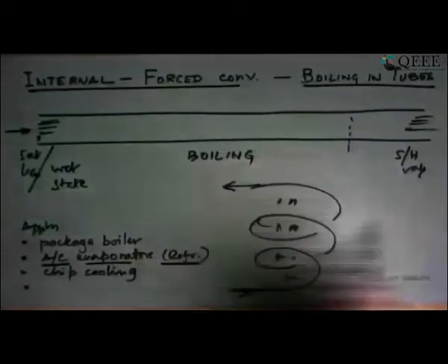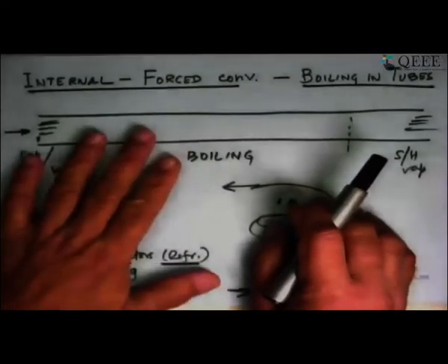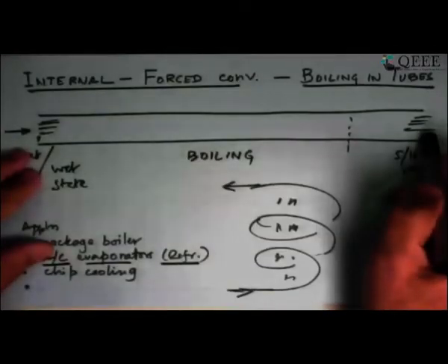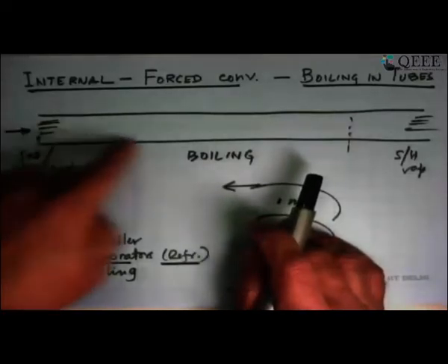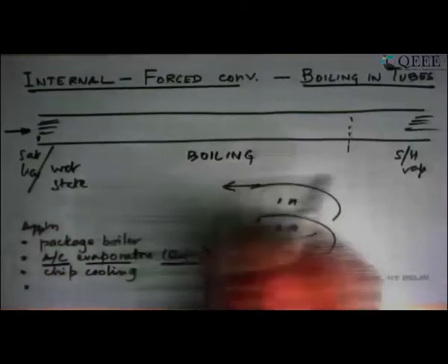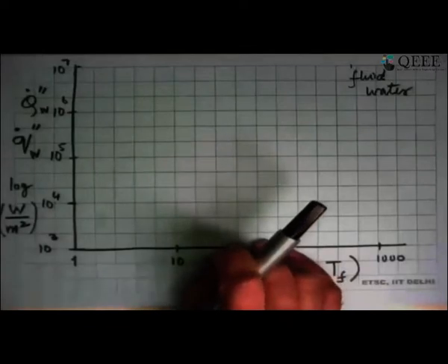In thermodynamics, in the first course in thermodynamics, we assumed this process to be an isobaric process. That was an idealization. It just helped us to solve the problem quickly. In the real world, yes, there will be a small pressure drop as the fluid goes through the tubes, and we would also be interested in finding out, as heat transfer takes place, how much the pressure drop is in the real case. So, isobaric phase change or isobaric boiling or condensation, as I have mentioned, is an idealization. In reality, there will be pressure drops. Okay, so that's the answer to the question.